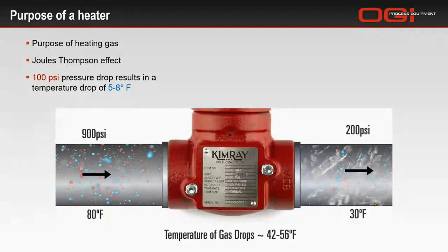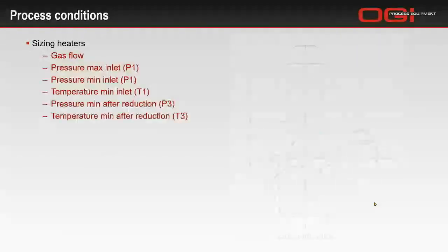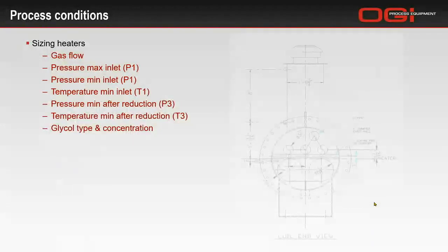And to be able to size a heater to keep it above freezing temperatures, you're going to need to know your process conditions. So to size your heater, I have these items here in red that are required at a bare minimum. If you have this information, any manufacturer should be able to quote you a water bath heater and put together a size for you.